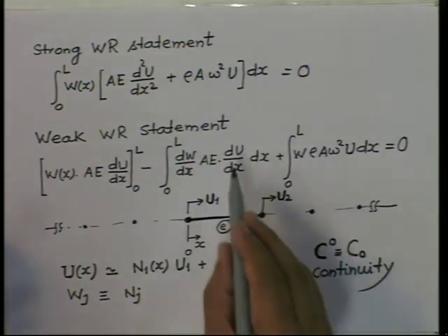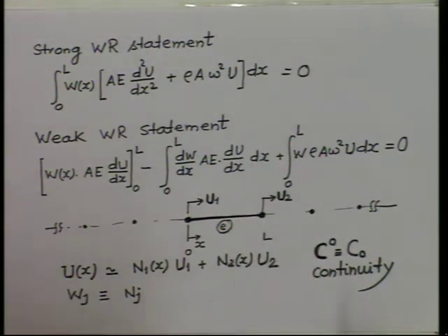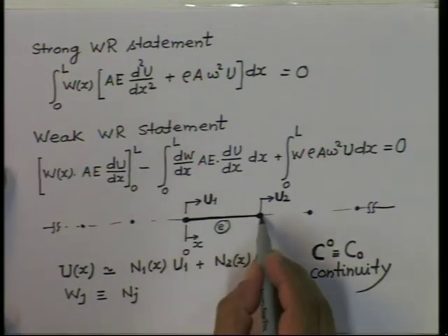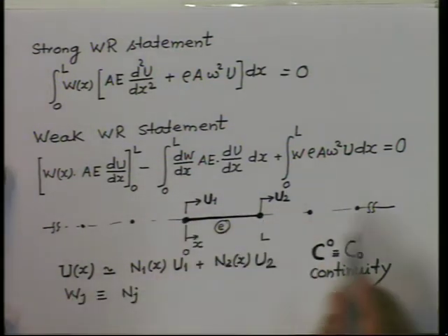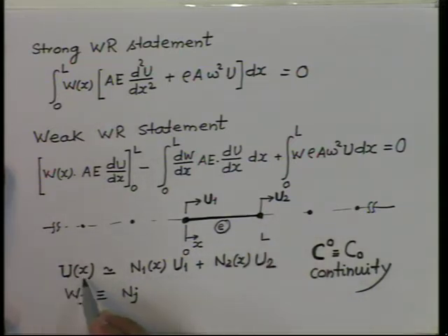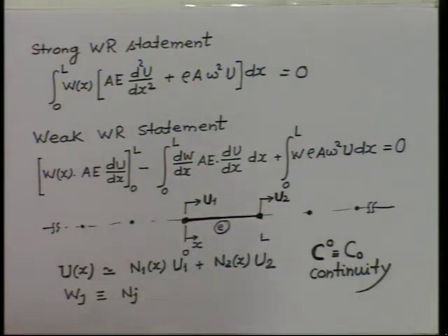Okay, we know that this u, now because this is only a simple two noded element, if you discretize this entire domain into a number of smaller two noded elements, then we can have this expansion of u(x) like this, N 1 u 1 and N 2 u 2, and then the weight can be fixed at, because there are two nodes now, N j, the weight for node number 1, the weight for node number 2. So, this is our standard practice, we are not doing anything new, we will just see what is the form of equation that we are getting, that is all.